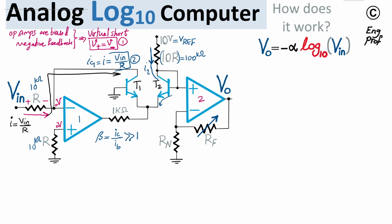Okay, so let's compute what this current is, say IC2 or I2. This I2 for transistor 2 is simply 10 volt, Vref, minus this voltage Vx, the voltage at the positive terminal of op-amp 2, divided by the 10R, which is for example 100 kilo ohm. Okay, so the next move is, let's keep Vref as 10 volt.